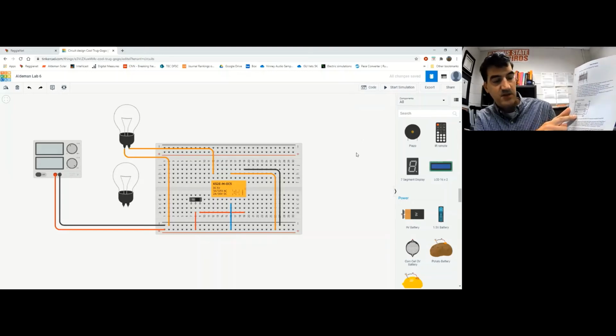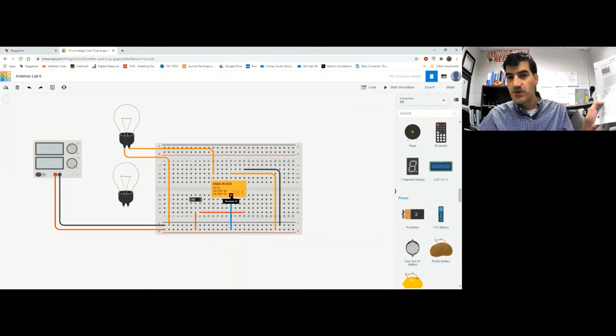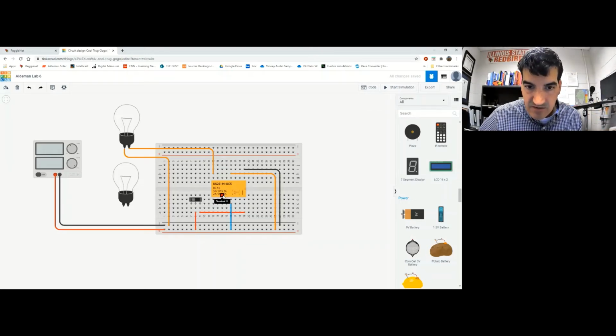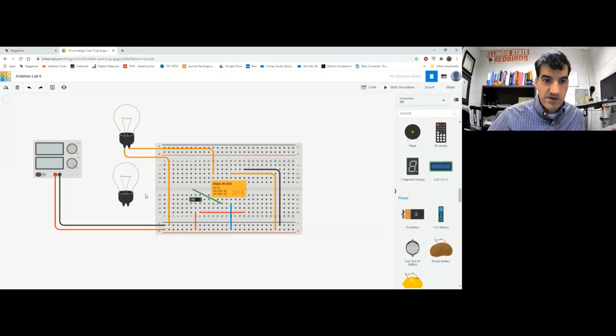Now we need to pick the normally closed contact associated with that common. So what is that? We need the normally closed contact associated with terminal 13, and that's going to be terminal 11. I'm looking at page 41, but you can also look at it right here. It's this one right here. This is going to be the normally closed. So I need to go from any of these in this row, so I'll pick this one. And where do I need to go? I need to go to the input side of PL2.